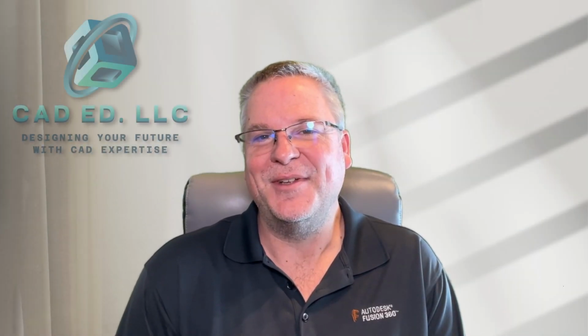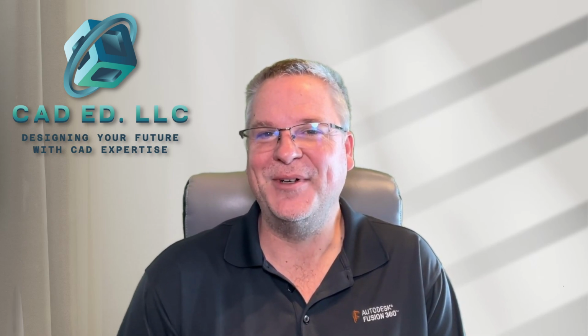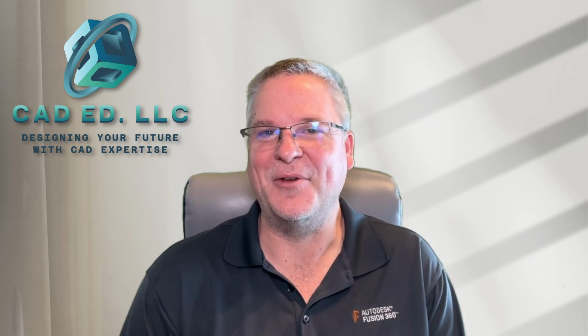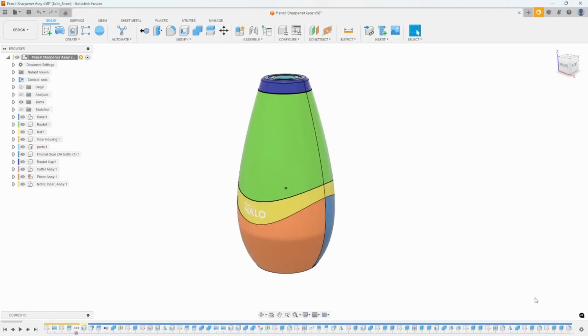Have you ever been using Fusion and suddenly your parts turn this pretty pastel color? Well, it's called component color cycling, and let me show you what it's used for and how you can turn it on and off. Have you ever been working in Fusion and all of a sudden all of your components change to this pastel color and you're not sure why? Well, it's probably because you accidentally hit Shift N on your keyboard.